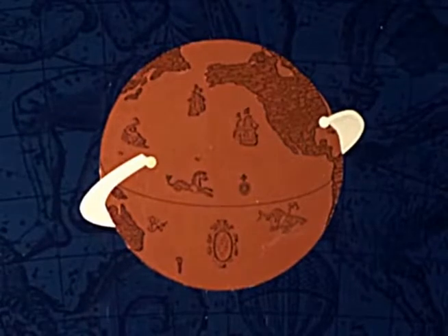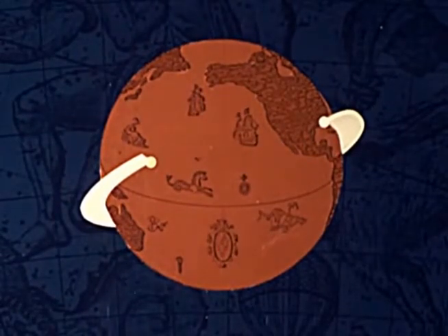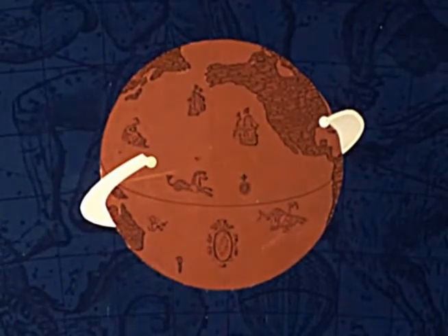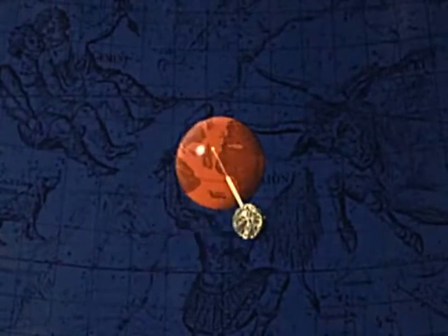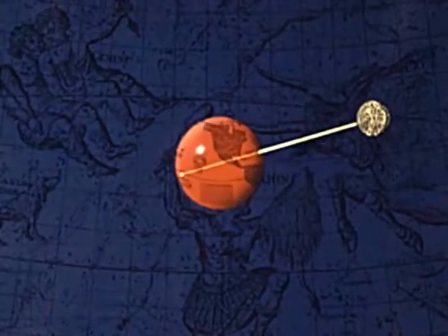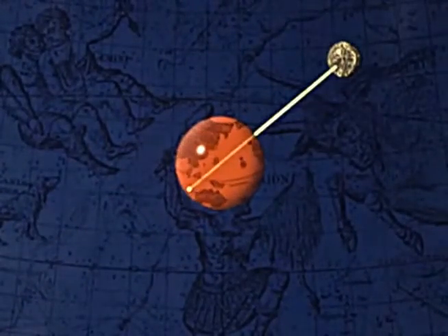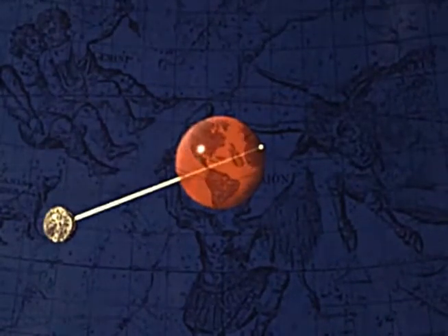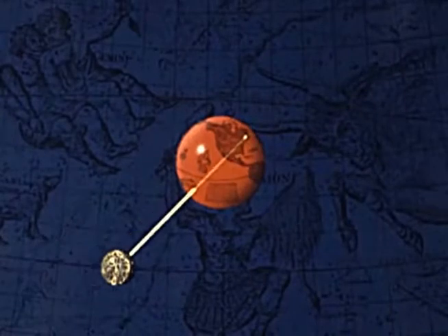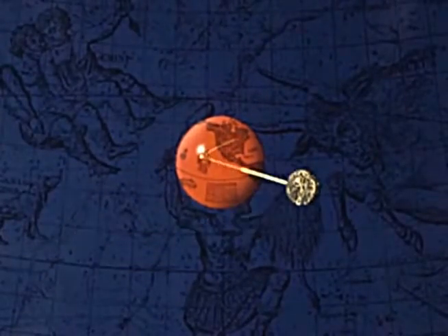We will also show how this is combined with the launch azimuth constraints to define the duration of the daily launch window. The movement of the antipode is caused by 2 separate motions: 1, the monthly revolution of the moon around the Earth, and 2, the daily rotation of the Earth on its axis. It's convenient to examine these motions separately at first.